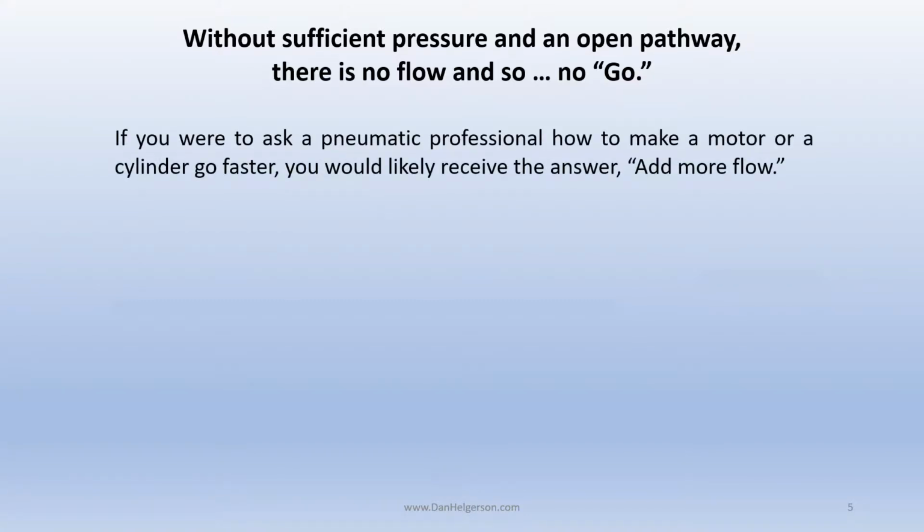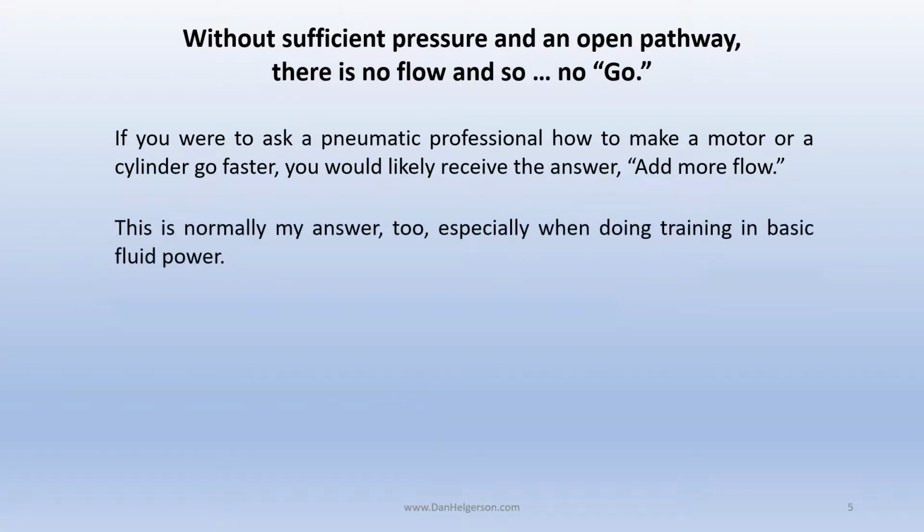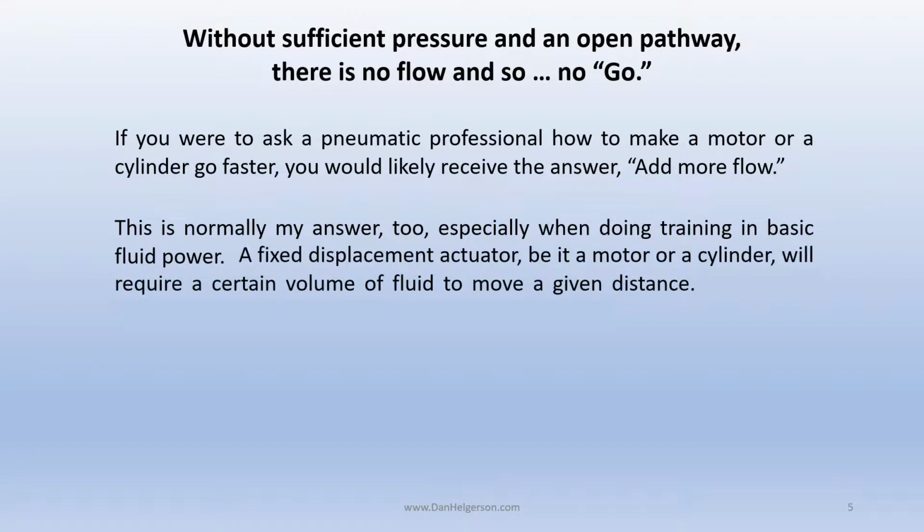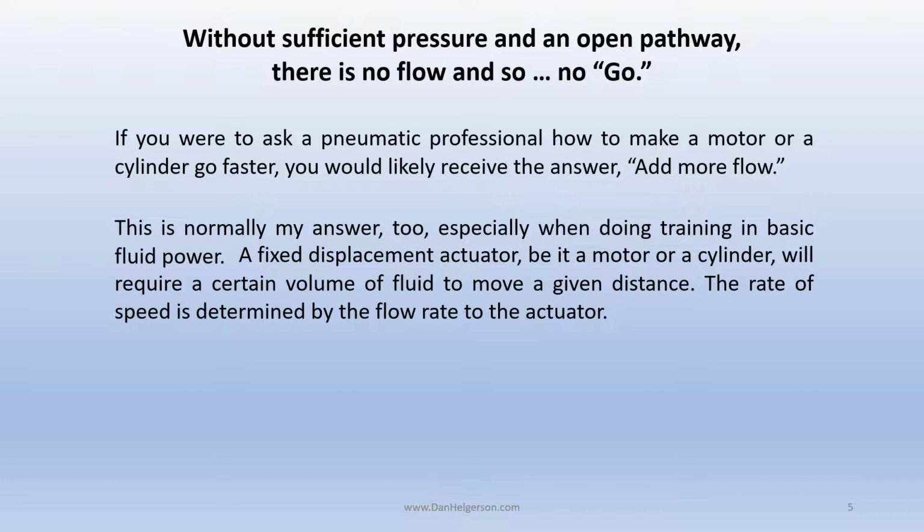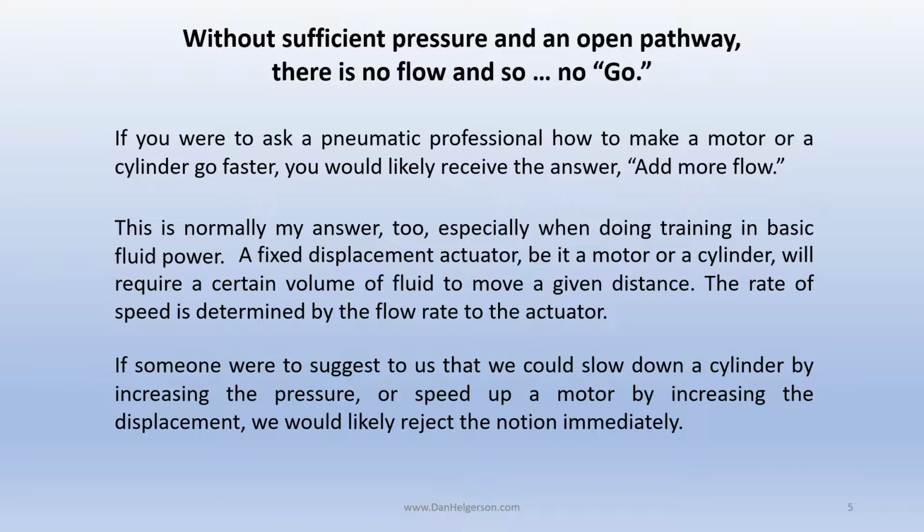If you were to ask a pneumatic professional how to make a motor or a cylinder go faster, you would likely receive the answer, add more flow. This is normally my answer too, especially when doing training in basic fluid power. A fixed displacement actuator, be it a motor or a cylinder, will require a certain volume of fluid to move a given distance. The rate of speed is determined by the flow rate to the actuator. If someone were to suggest to us that we could slow down a cylinder by increasing the pressure, or speed up a motor by increasing the displacement, we would likely reject that notion immediately.